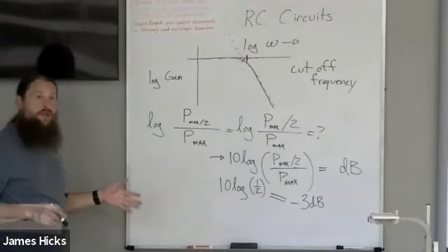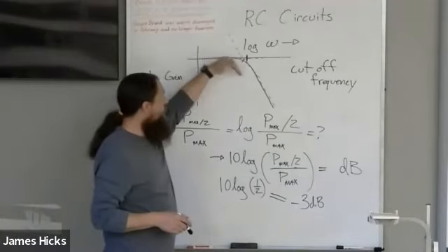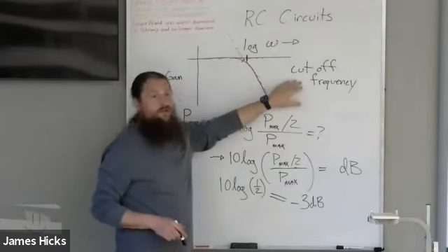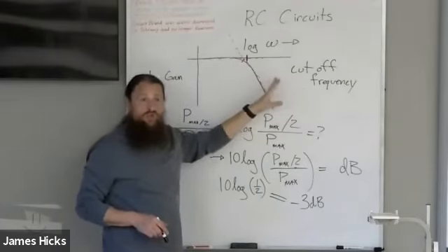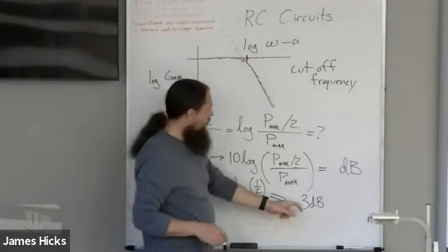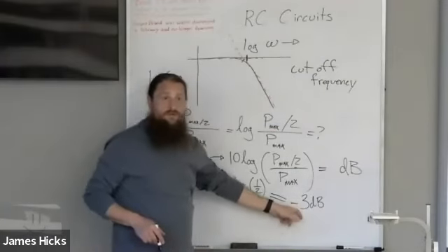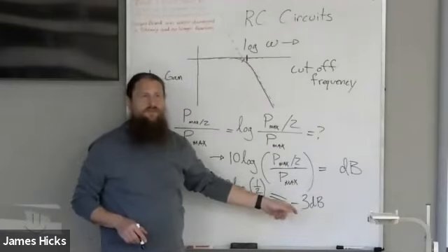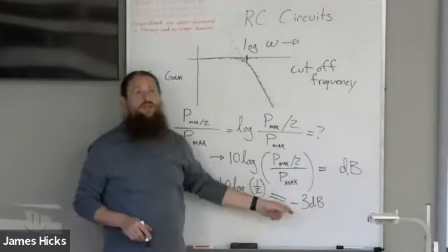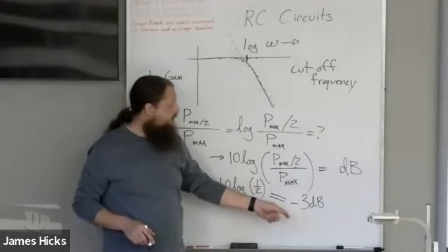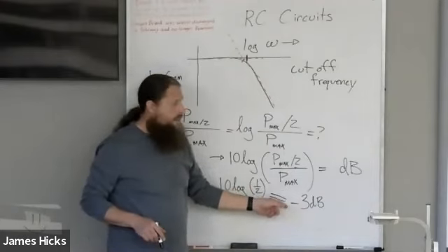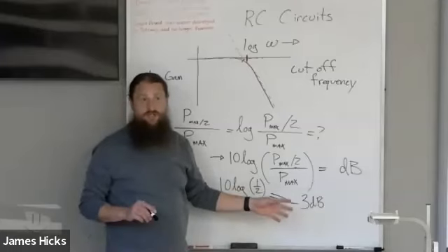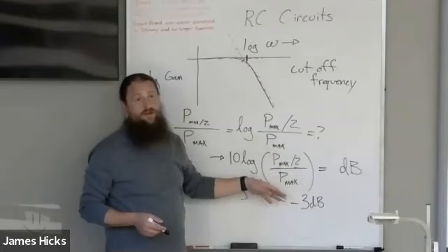So that's how we characterize when this curve starts to go off. This cutoff frequency is usually taken to occur at the -3 decibel point. Sometimes this is called the 3 decibel breakpoint. A change of 3 decibels corresponds to a change in intensity by a factor of a half.